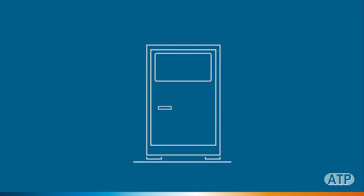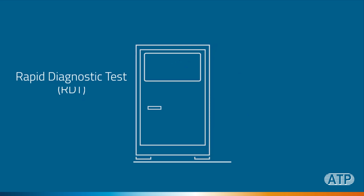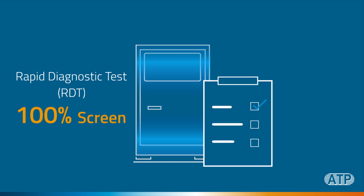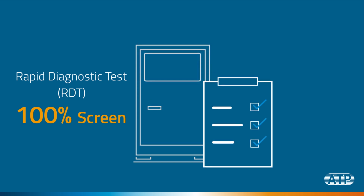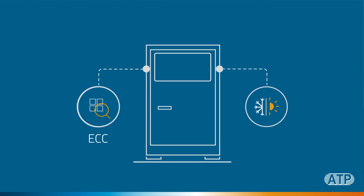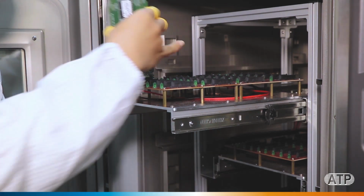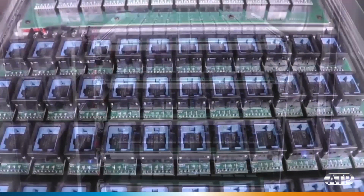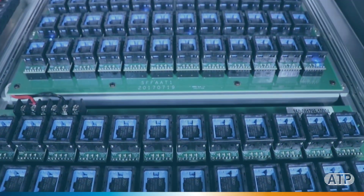At ATP, we call this process Rapid Diagnostic Test, or RDT for short, where we conduct 100% screen on every device in every area of the drive with our self-built proprietary tester. There are many parameters tested under RDT, but for simplicity's sake, I want to highlight the two most important elements, which are the ECC and temperatures. As an example, let's dive in on how we make SSDs that can operate from -40 to 85 Celsius.